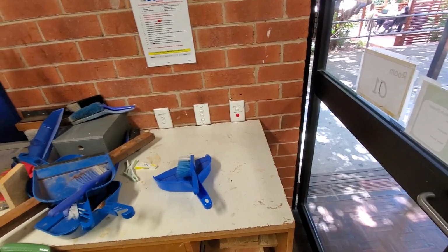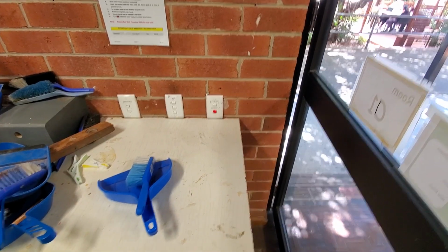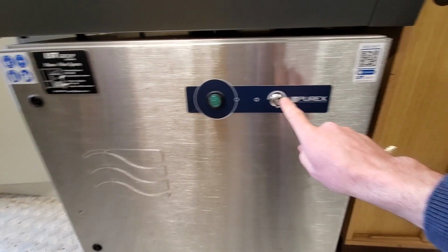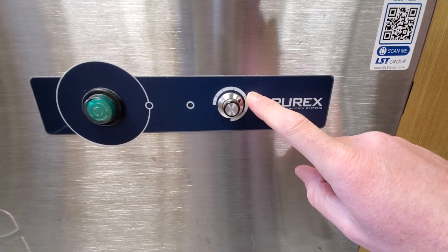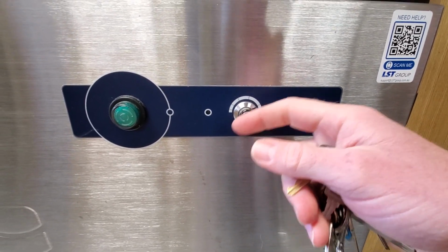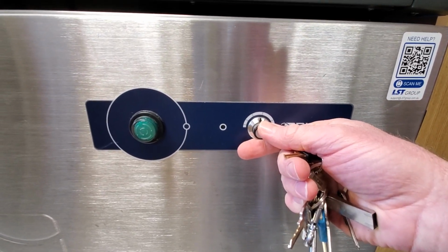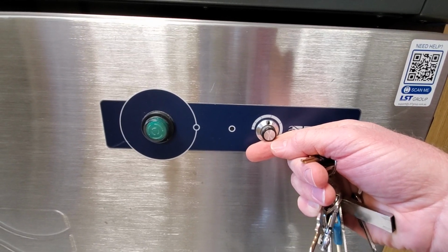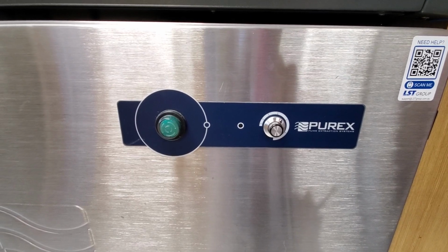So pretty much leave that on all the time, but sometimes people turn it off because they don't know what it is. This is the filtration unit, power button and a flow control. Usually about 1 o'clock position works fine for most things. If you're generating more smoke for some reason, you could turn it up a bit. 12 o'clock would be about the minimum for anything we would normally use at school. So if you just leave it there and keep an eye on it, things should be fine.